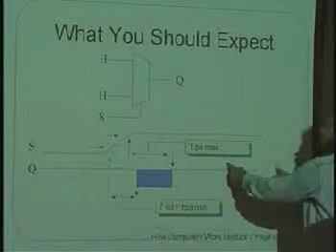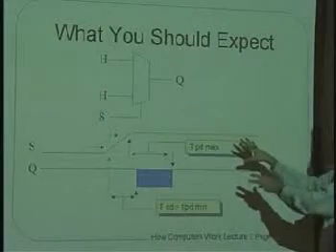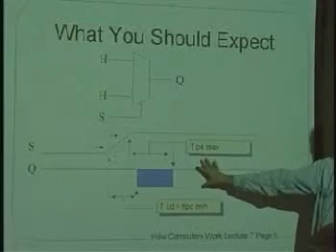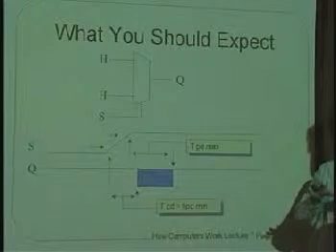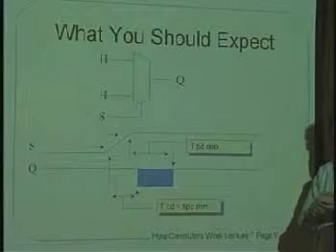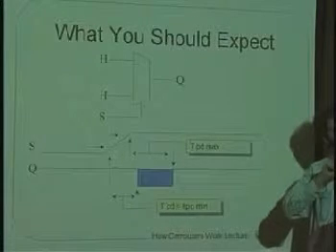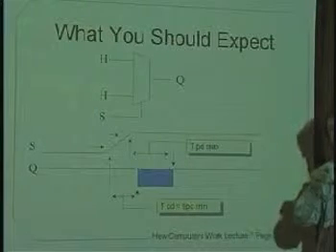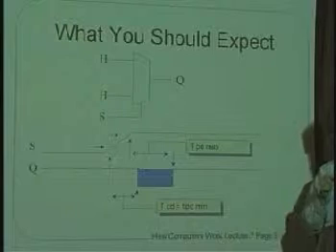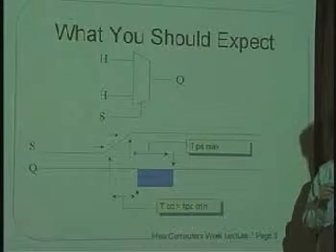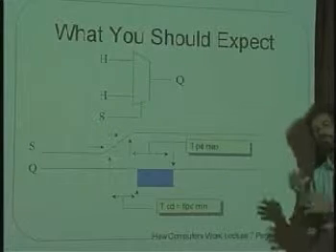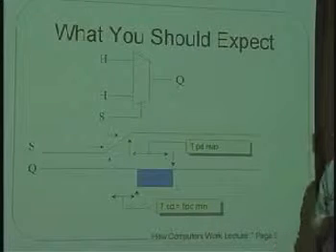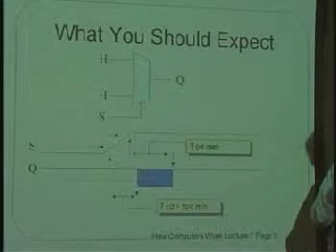There is no relationship in this picture here that says TPD max is more than TPD min. Nothing in this picture proves that. Right. Okay? I'm telling you that in general, TPD max is bigger than TPD min. Would it be less than TPD min? Because we've inserted this difference between valid and invalid, according to that definition, one could imagine a circuit in which that were true. In truth, there are no circuits like that, okay? But from what you guys know so far, there's no reason to believe that the max should be bigger than the min. Except that it is. Okay? And you'll see why later.